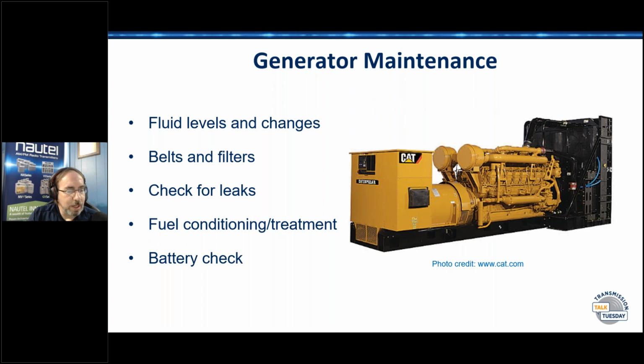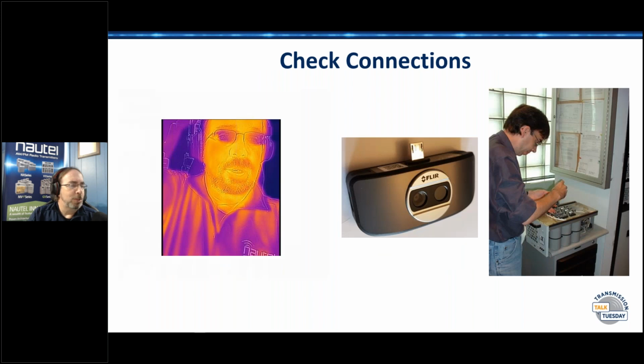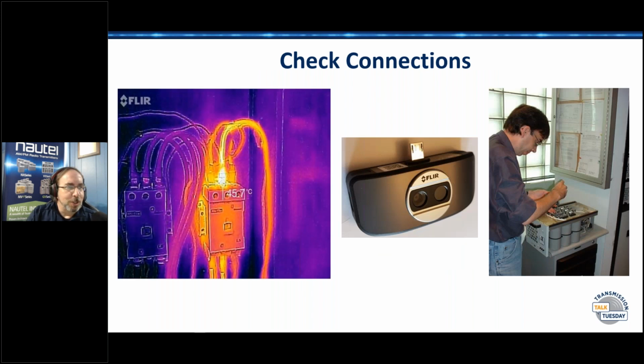Thanks, I appreciate that. Moving on, and Mark, thank you very much for that input, because that was useful as well. I have got more things going on here than I've got brain power to deal with. One of the other things I tell folks a lot, and I've beaten this drum, and I'm sure anybody who's watched this has seen it, is that I am a huge fan of this little FLIR infrared camera. The great thing about the FLIRs is that you can walk into your transmitter site, hook it up to your phone, and aim it around and see what's hot at the transmitter site.